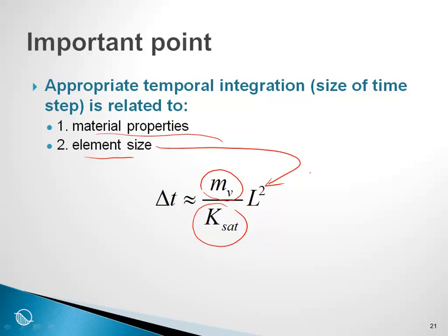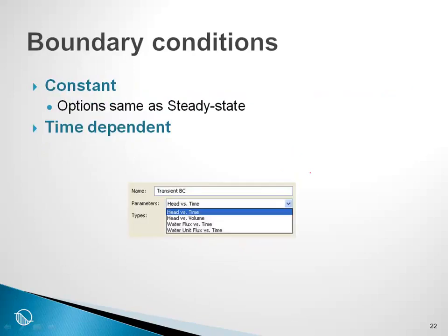The important thing is we get irregular results and unreasonable results sometimes if delta T gets too small. So we cannot say, I will make delta T infinitely small and get the best solution. Unfortunately, that doesn't work. Also, we cannot make delta T too large, because in a nonlinear process we need to step along the nonlinear process in appropriate delta T's. We can't step from one end to the other. That will give us the wrong solution.